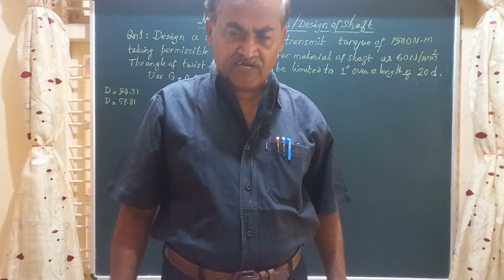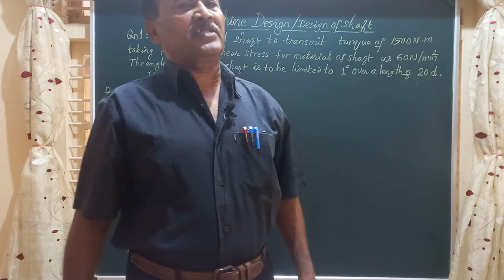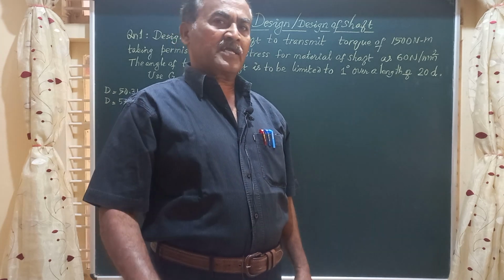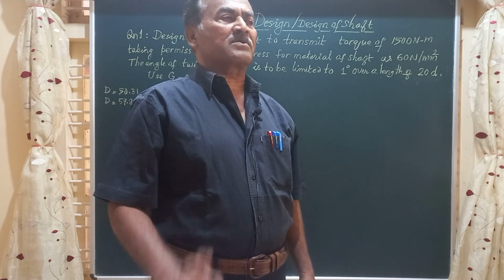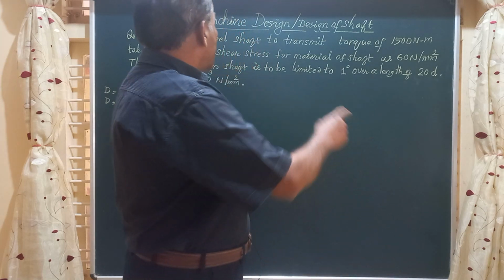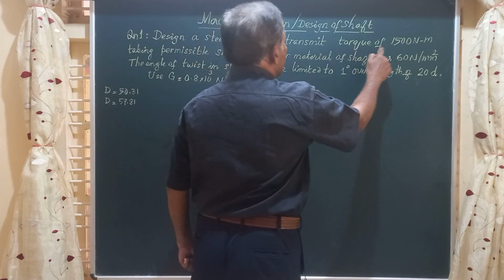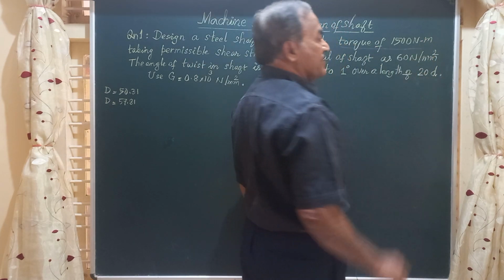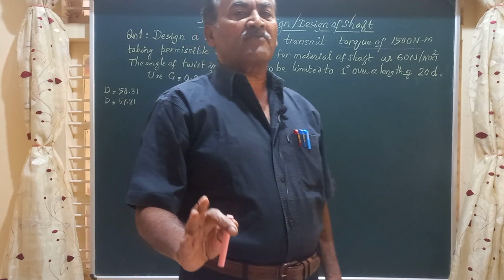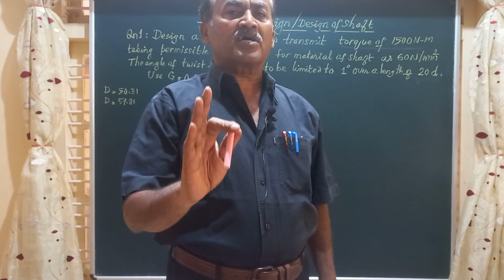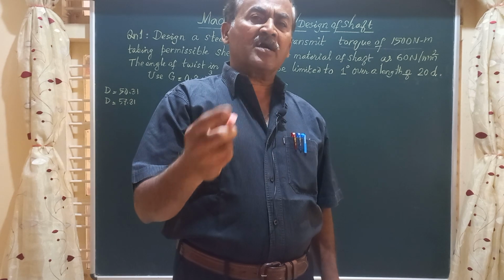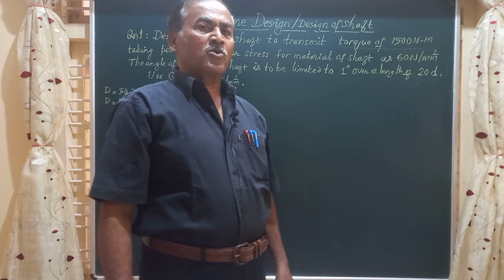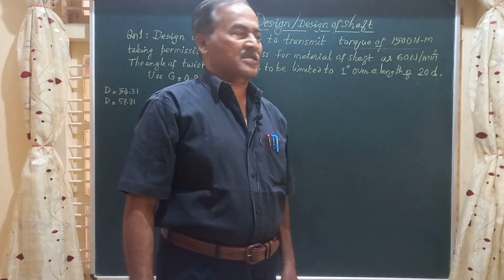Friends, first of all, in the design of any of these shafts, you should first find out to what type of load the shaft is subjected. Here it is clearly stated it is transmitting a torque of 1500 Newton meter. So the shaft is subjected to just torsion only. The torque or torsion is called by other names such as torsional moment, twisting moment, etc.